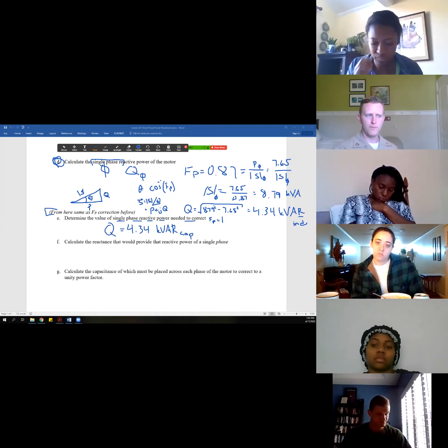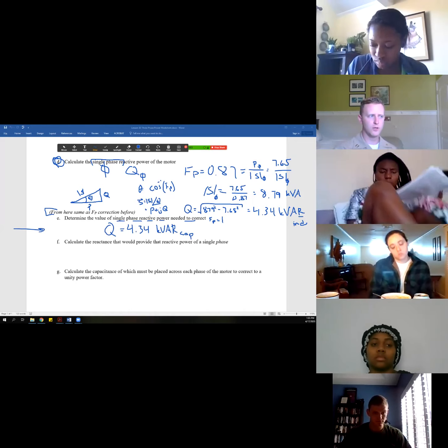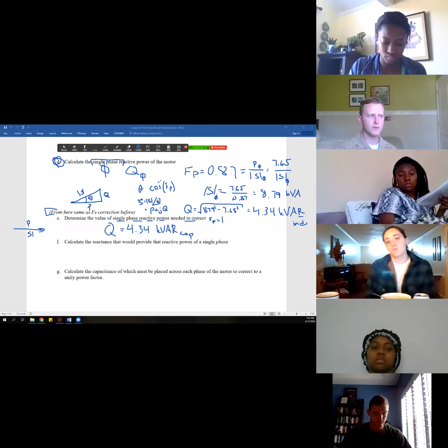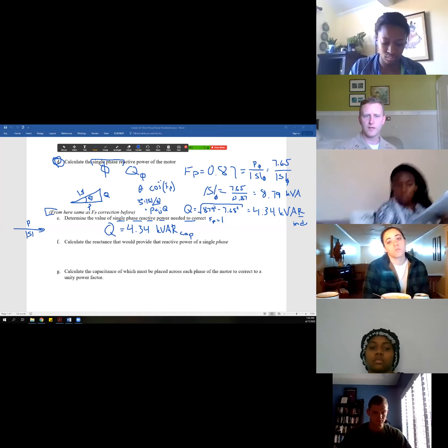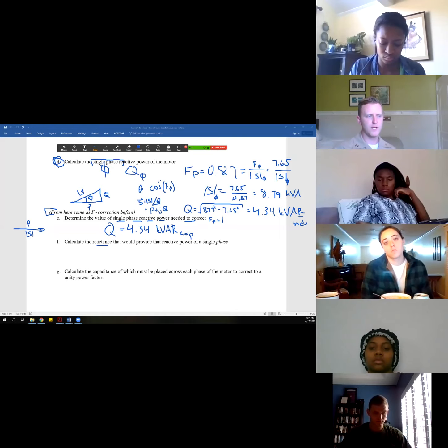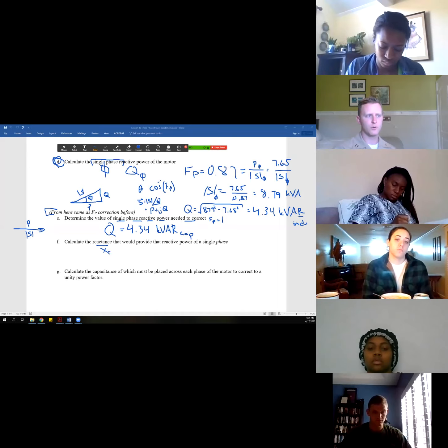All I need is to take what was an inductive, replace it with a capacitive. And those two Q's will cancel, so that what was a power triangle, the Q's equal 0, and P and S are equal to each other, right? That's power factor to unity. The Q's will sum to 0. So now we're going to find the reactance that we need. Well, if we need to do this, it says capacitive, so we're solving for X sub C.